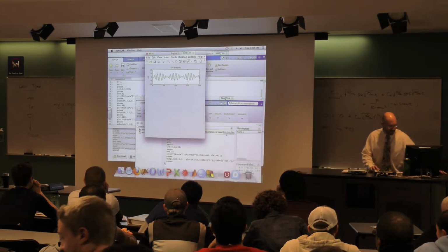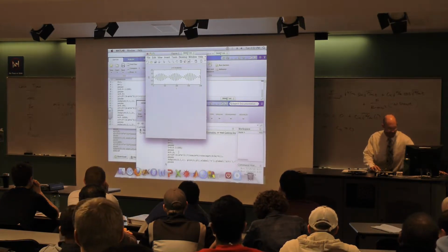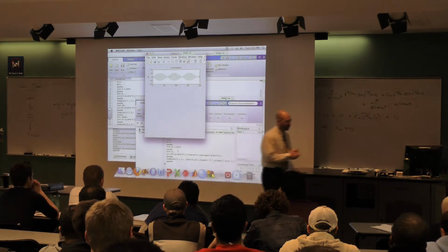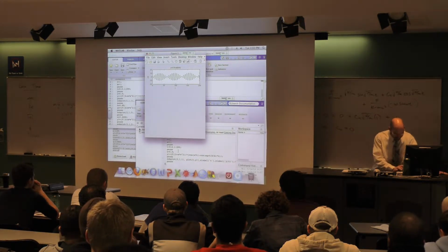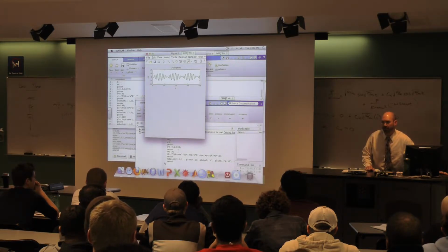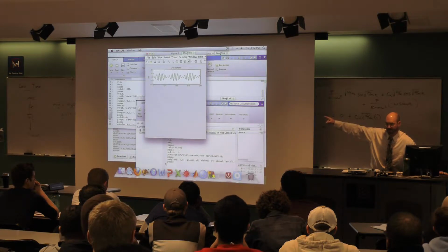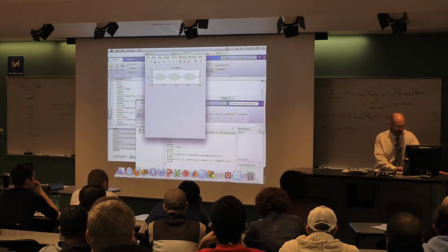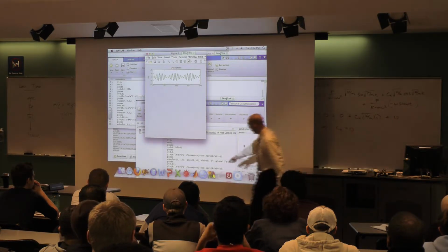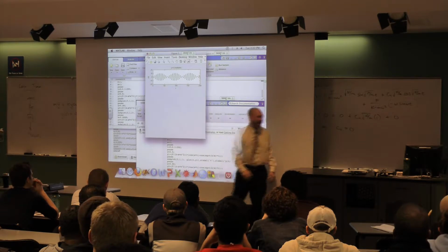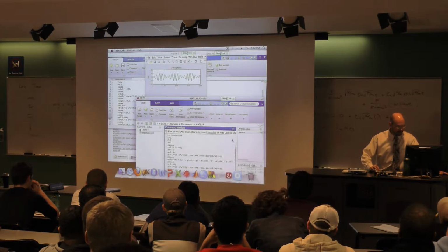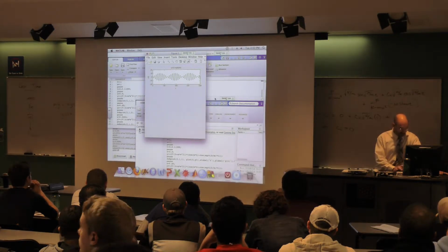So now what happens, but I'm not really there, right? I'm only at 90%. You get this kind of behavior when you're a significant percentage of the natural frequency, but not completely there. By the way, if I'm flying an airplane and the wing is doing this, is this good? No. Probably not. Let me show you what's worse. What's worse is if I get 99% of the way. Down here, omega now is 0.99. If I'm now 99% of the way there, here's what the solution looks like.